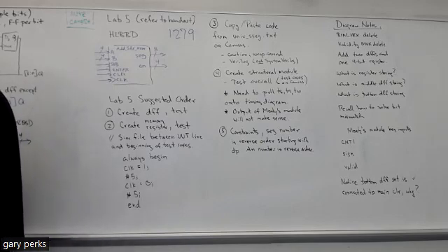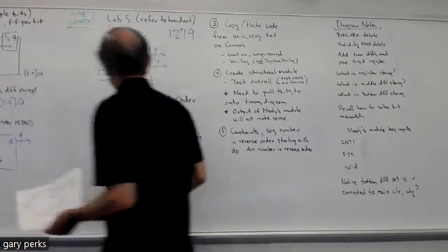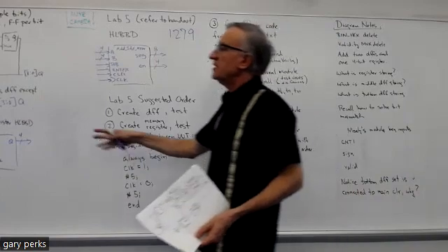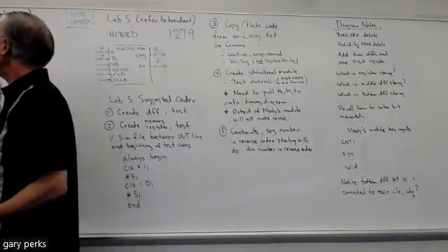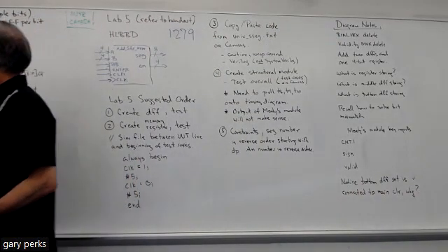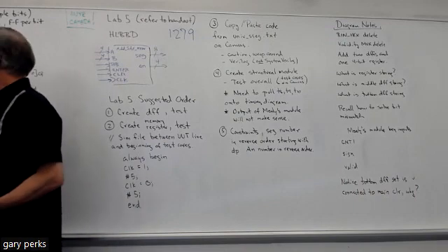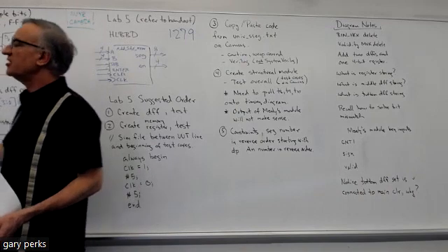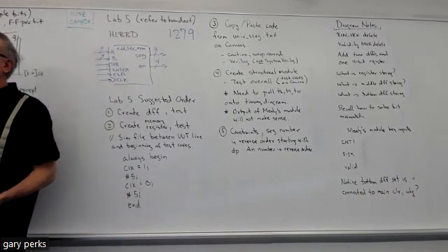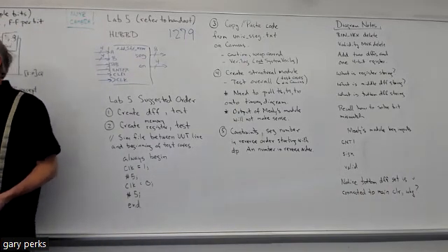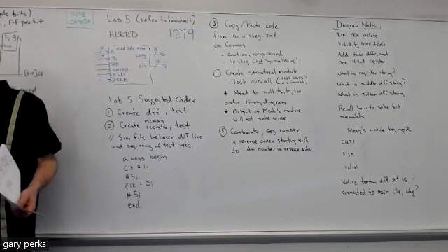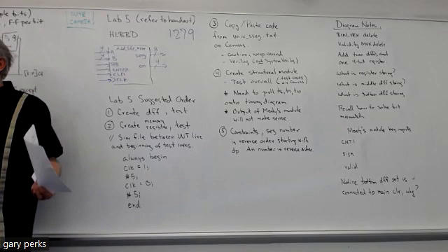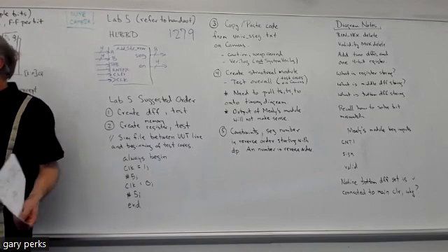All right, so that's testing the D flip-flop. Now, as I said earlier, since you're modeling the 4-bit memory register with the same code, except you're making these few edits, like 4 edits, the way you would test the memory register is with the same test cases as with the flip-flop, right? Because you're testing the same thing. The only difference between the register and the flip-flop is that the register is 4 bits and the flip-flop is 1 bit. Other than that, they operate the same.